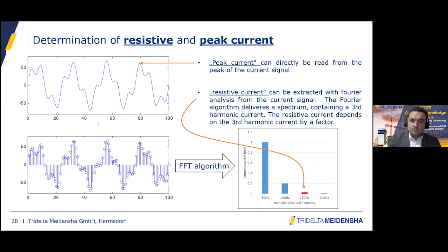The only thing we found is that it is possible to compare three surge arrestors of the same make standing beneath each other on the same system, and to measure the surface temperature. You always measure surface temperature on a cold day, because then the sensitivity is very high, and you will greatly see differences between those three surge arrestors.